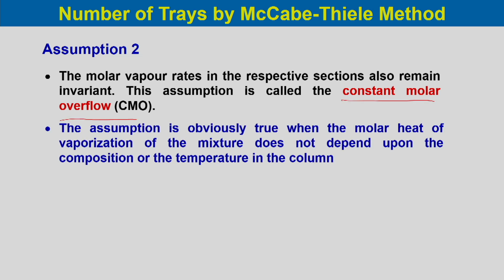The assumption is obviously true when the molar heat of vaporization of the mixture does not depend upon the temperature in the column. So, this assumption, constant molar overflow for the vapor, will be true when the molar heat of vaporization of the mixture does not depend upon the composition or the temperature in the column.